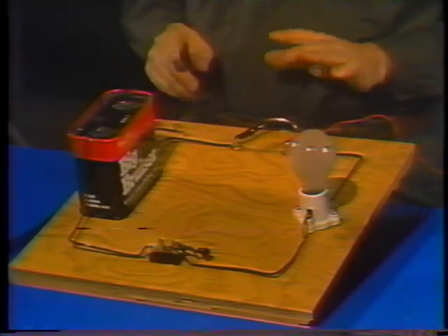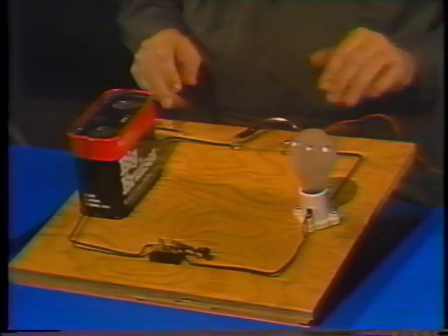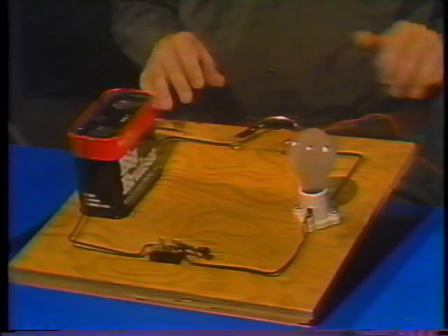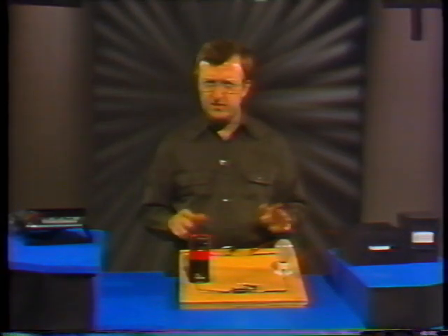Now, there's a name for this kind of connection. It's called a series connection, because all the current that flows through the circuit must pass through the meter. You always set an ammeter up in series with the circuit, otherwise it won't measure all the current. Now, we can close the switch and take a reading. Well, we get around 1¼ amps. So we know that current is flowing through the circuit. Let's open the switch and remove this meter from the circuit.